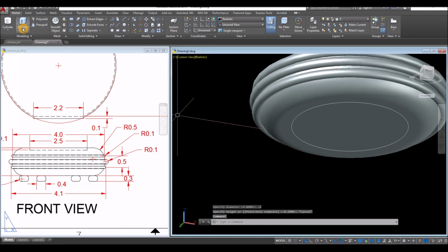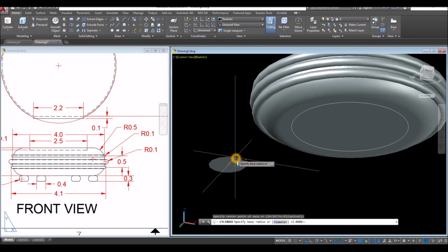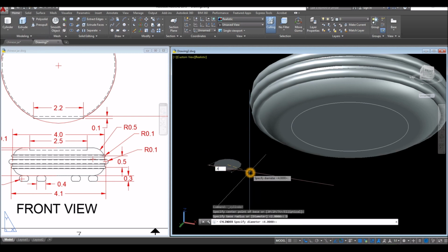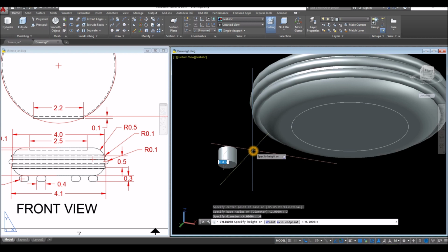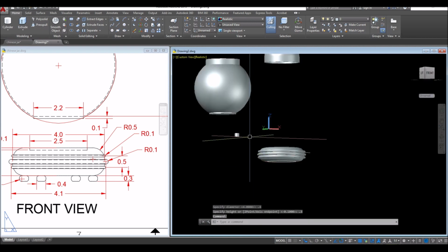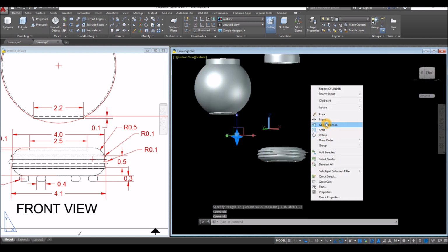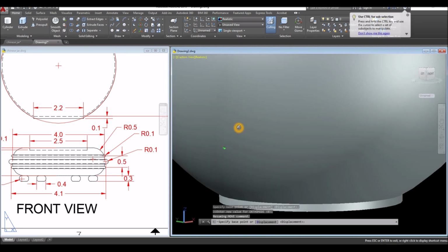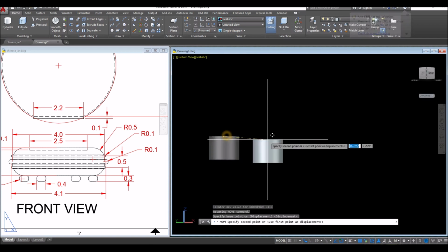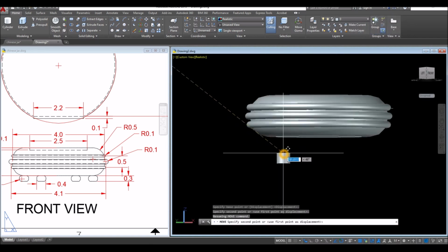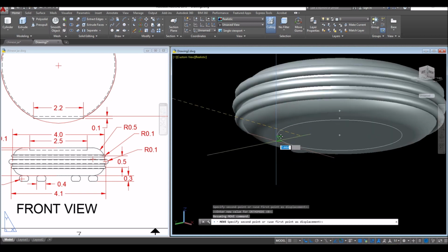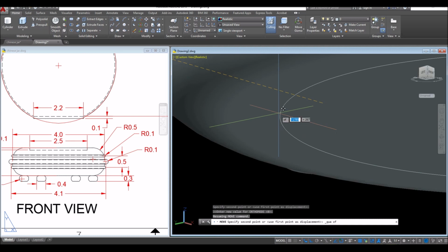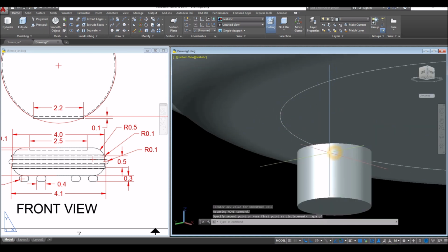There you go. All right, again, cylinder. Right click, diameter, enter 0.4. Bring your cursor upward and enter 0.3. I'm gonna bring this one closer. Move from center to the quadrant here. Attach it to the quadrant, so shift right click and select a quadrant somewhere here.